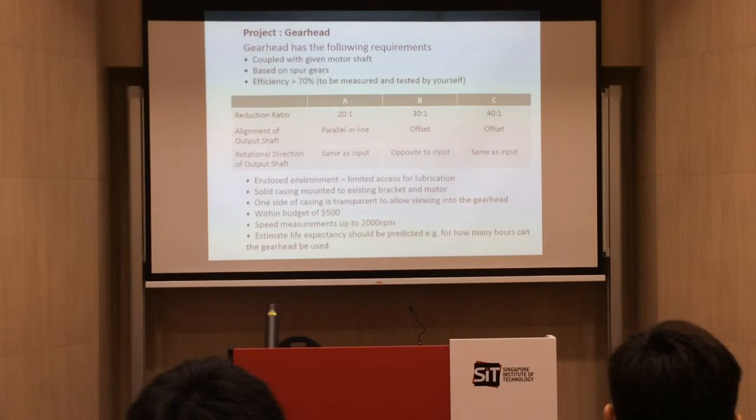So if you put your transparent part here, this is the biggest part. If something breaks, it will definitely break the transparent part, and it may also cause injuries because this thing will break easily. Broken parts will fly off. So I always advise, either this side or this side. I would advise you to put the transparent part on this side and this side. Basically, not a lot of plate is perpendicular to the rotation of the shaft. Because when something breaks, it only flies off this way. It doesn't fly off this way.